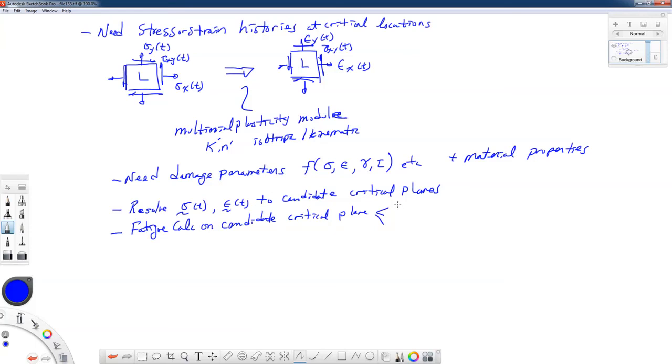So let's write in here rainflow, and part of the rainflow is peak picking and rearranging the time history and all that kind of good stuff that goes in here. Damage calc, and then accumulate damage. And then it gets easier after this part.